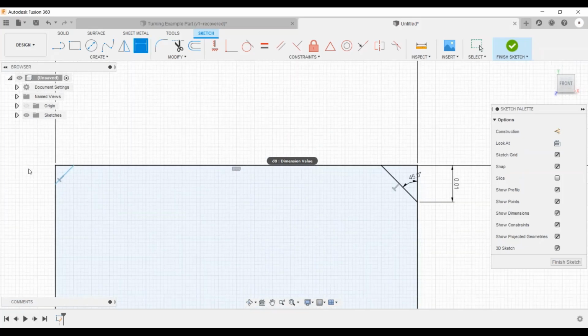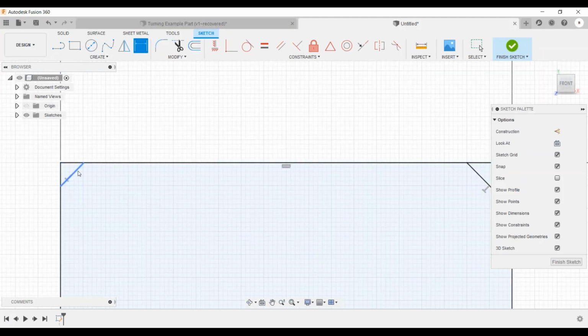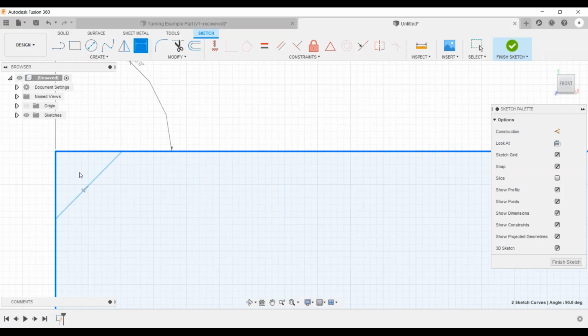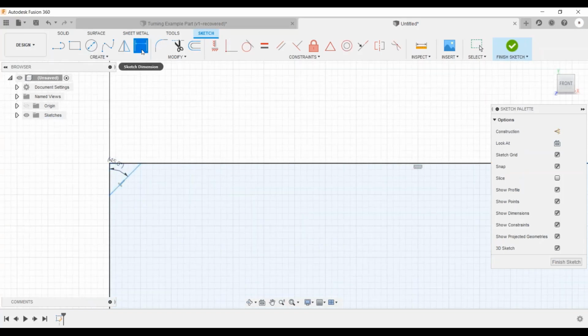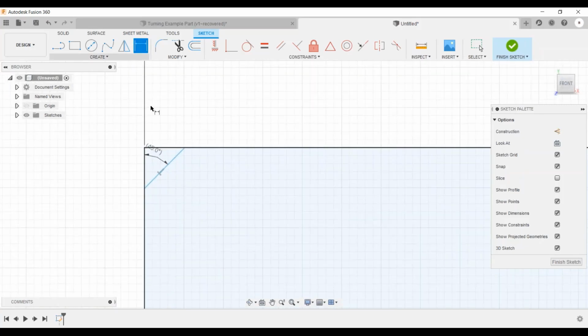And then using the one on the back, we can actually just copy the dimensions that we created from the front. So if I use our dimension and I pull up the angle here, and let's make sure we zoom in and get the right ones. So we got a 45 there, and we've actually already constrained it to the same as the front one, and then we can add a size to this one.